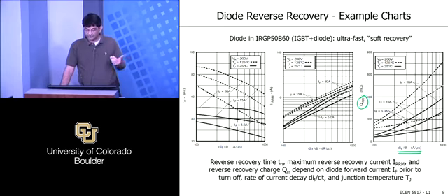If you have higher temperature, then you will see that you have more charge in there, because at higher temperature there is more charge, and so QRR goes up with temperature. So these dashed lines correspond to higher temperature. And then the other thing that's shown here is how it depends on the initial value of the current. If the initial value of the current is higher, you have again more charge in the diode, and it takes longer, so you have to pull more QRR. QRR goes up, right? The other factors are also similarly related, and it all makes logical sense, but the relationships are fairly nonlinear and complicated. Right? If you're interested, you can kind of look into this.